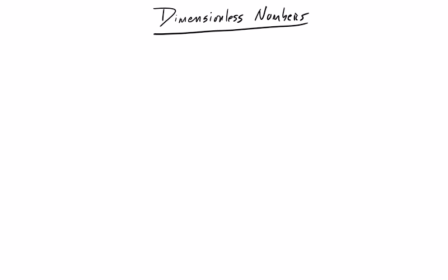All right. So the question is, what is a dimensionless number? Let's start with a dimensional number that you're aware of. Let's say we're talking about force. We've talked about force a lot in this class. We talked about surface tension and forces on curved planes and things like that. So force is a number, and it has units of newtons. If I say something has a force of 10 newtons, in SI units that's kilograms meter per second squared. That's a dimensional number. We could say pressure, and that's dimensional, in pascals, which is equivalent to newtons per meter squared. So these are all dimensional numbers.